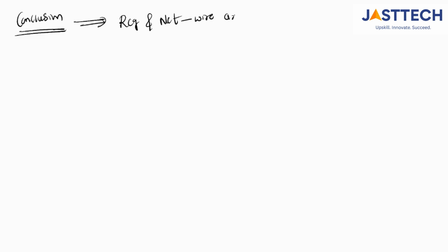Wires are unsigned data types. Unsigned data type means whether you are giving negative numbers, it will normally store in terms of 2's complement, but when you want to display the 2's complement number, it will display as a positive number only. That is nothing but an unsigned data type. Hope you understood. Any doubts or queries? Shall I move forward?